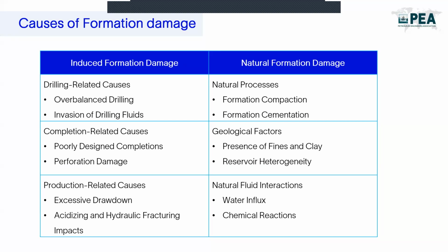There was a field that is being drilled with a certain mud pressure. So the hydrostatic pressure at that mud pressure was considered in the early stages of the field. But after 10 years of production, the reservoir pressure reduced drastically. However, unfortunately, the same hydrostatic pressure was being applied even after the depletion. So it has been noticed that almost all of the wells that were drilled after the depletion have never produced.